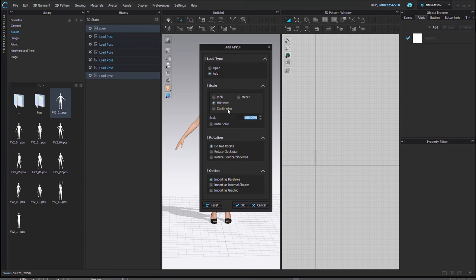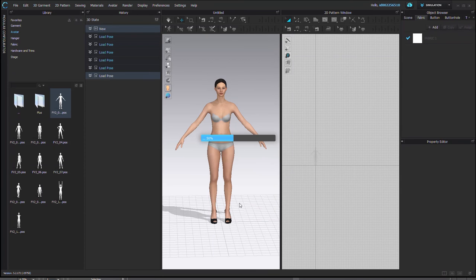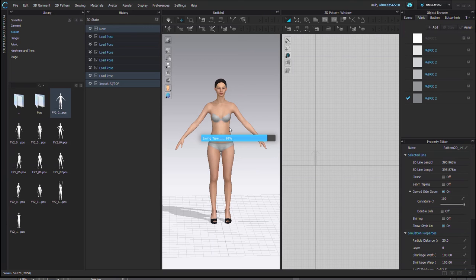And when I choose auto scale, or when I uncheck it, it seems to say like 100% is in the millimeter option, and it jumps up when we put it in the inches option. So I'm sticking with the millimeter option, and we want to add it to the model or the project we're working on. And we are going to hit OK.